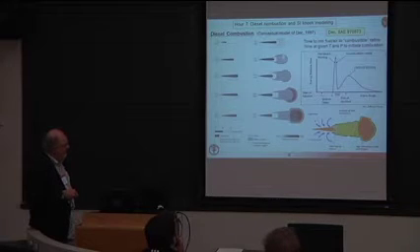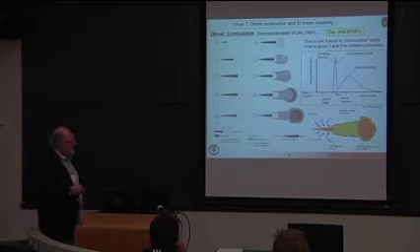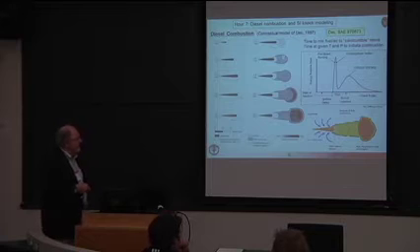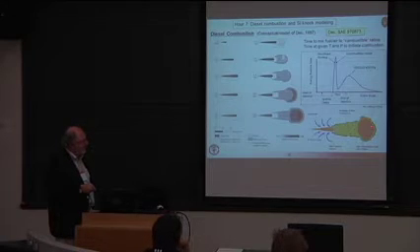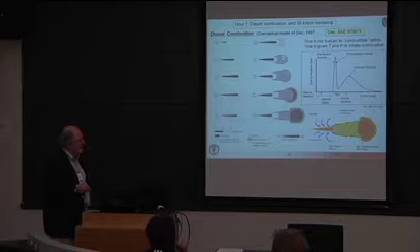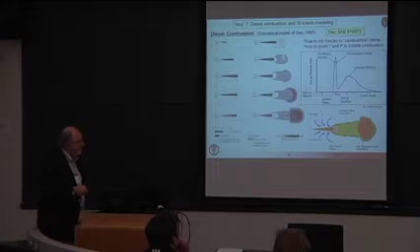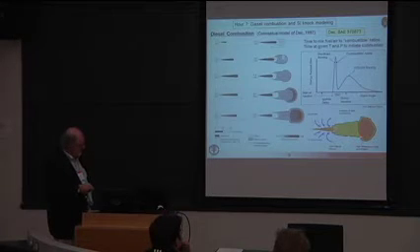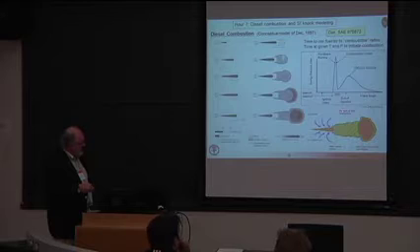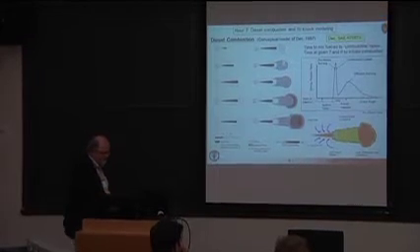So in this graphical illustration here, you have liquid fuel, air being entrained due to the high velocity motion of that liquid. You have this kind of fuel preparation region here, a rich region where soot precursors are being formed and kind of low temperature combustion products. And then finally, this region here where there's a shortage of air. There's still some entrainment, of course, but here's where you would see quite a bit of soot being produced. And this thin line you see here is the diffusion flame that separates the fuel region from the oxygen.